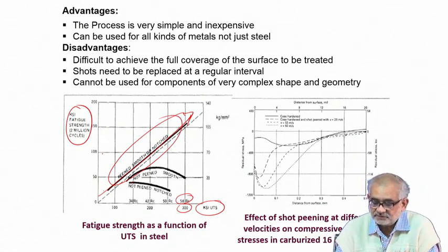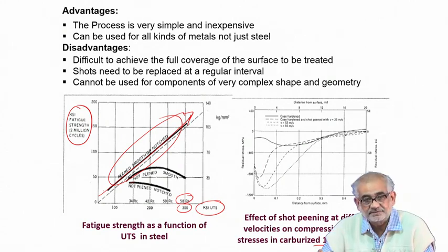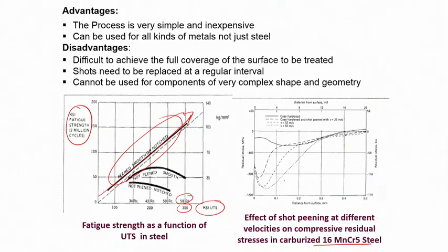In fact, for a given steel, which is carburized steel, now normally we haven't discussed as yet, but carburizing treatment followed by a certain surface thermal treatment develops predominantly martensitic microstructure. And when we develop martensitic microstructure, then we may expect that the state of stress onto the surface is residual compressive in nature. But what is shown here is that for a carburized steel, this is the neutral plane. So obviously this is in the compression zone.